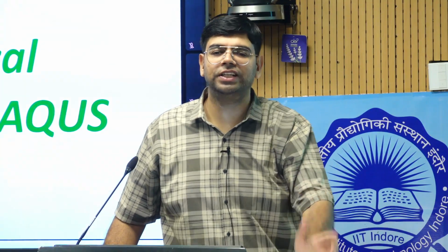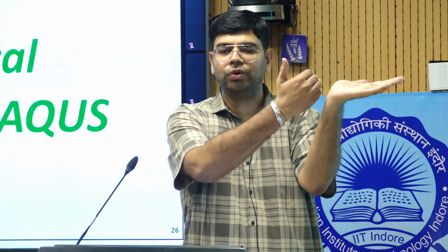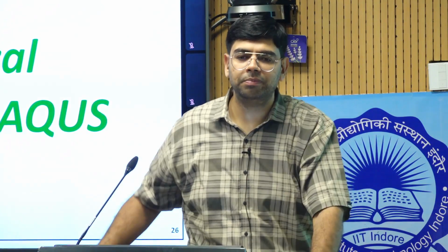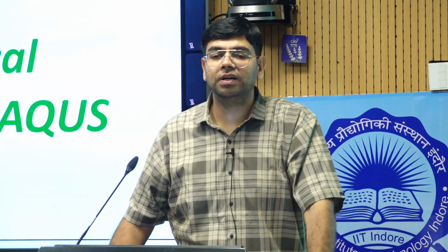And you have to fix the component. For example, if you want to develop a bending actuator, the edge is going to be fixed. So you are defining the boundary condition to the clamped edges at this location and pre-stretched to the membrane. You're getting my point? So the next step is post-processing.